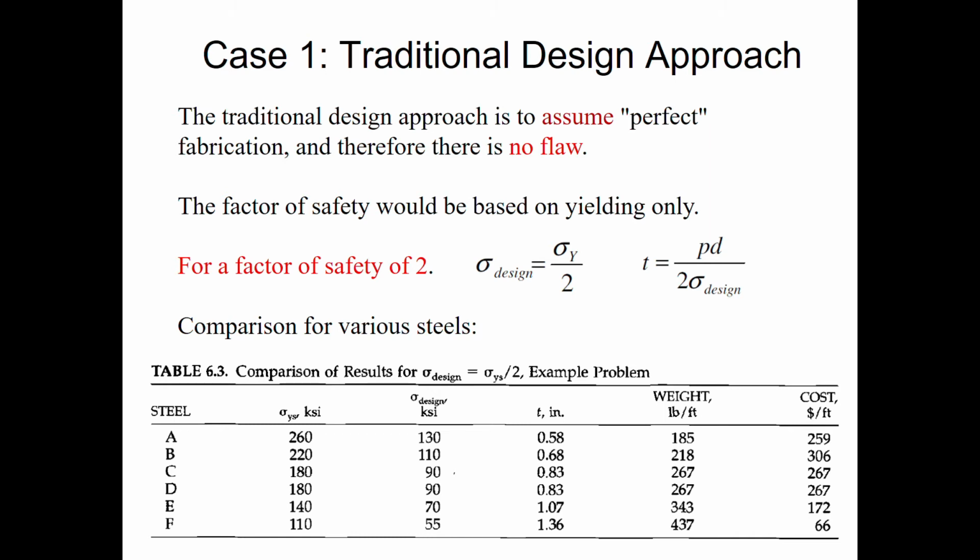For example, if a structure can stand 100 kilonewton when we calculate, and the factor of safety for that geometry is 2, you should increase that 2 times from the one that you calculated. It means it can stand up to 200 kilonewton. Just now it was 100, now it becomes 200.